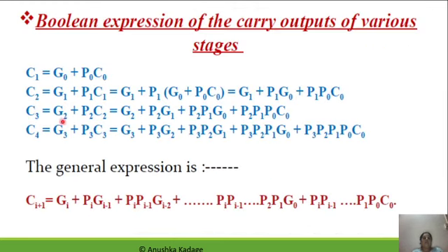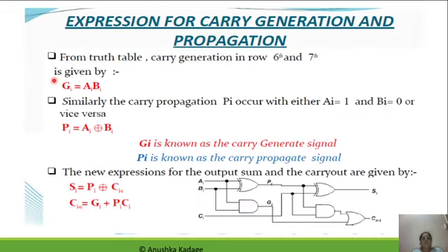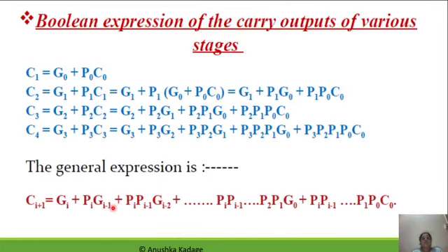And for that, first we will go for the C out that is to be generated, because this C out is going to tell us what the generated carry will be for the next stage. So C out is nothing but Gi plus Pi Ci. So let's say I am going to generate the carry out from the first stage, but actually it is doing the operation for the LSB bit addition.